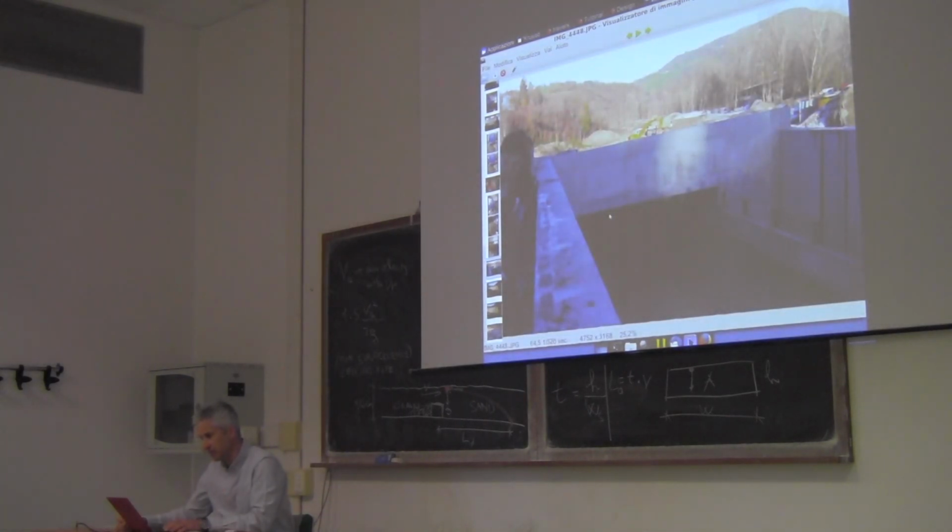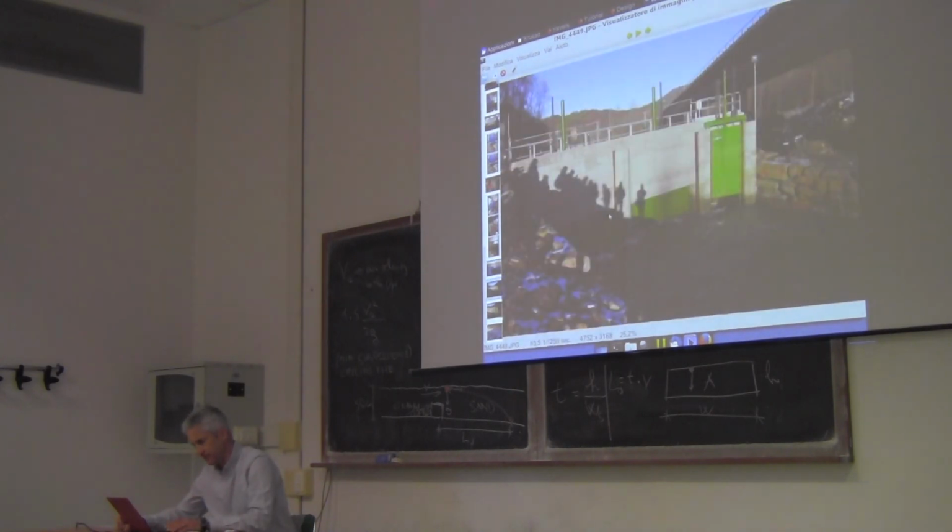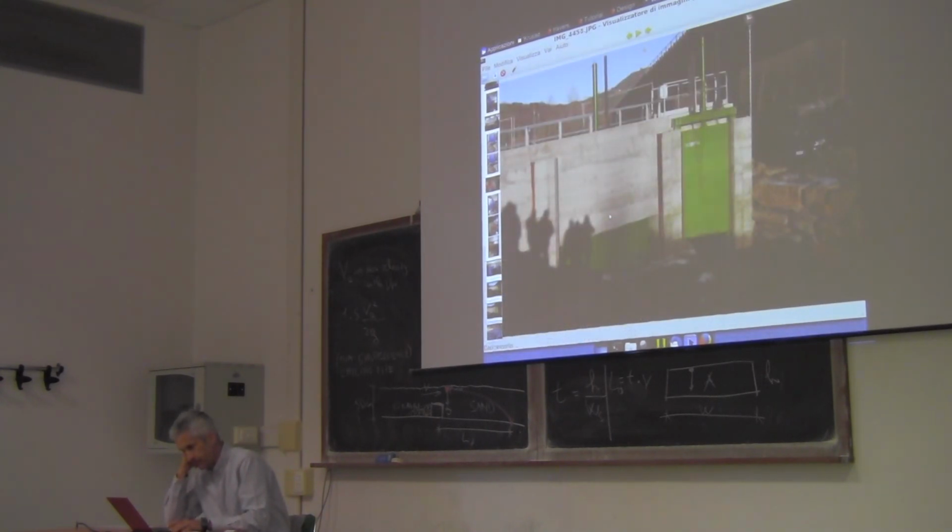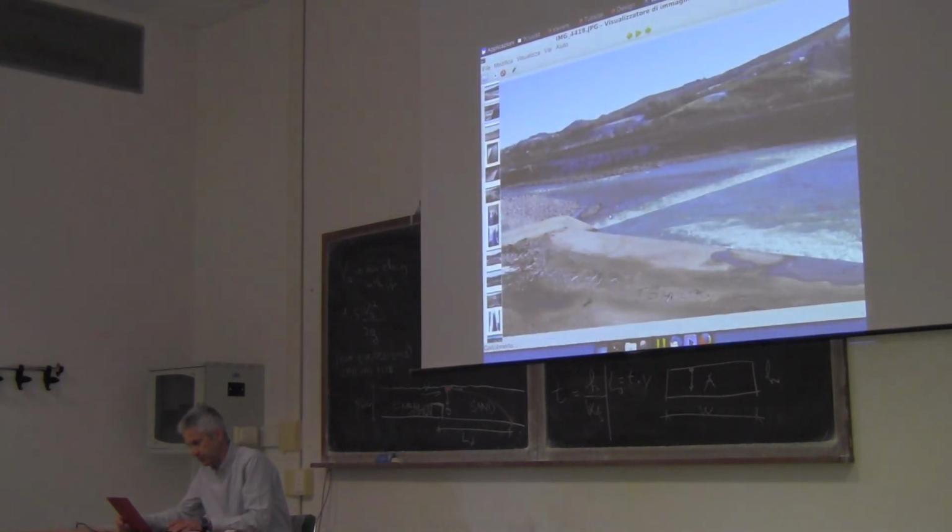And this is the canal that you have seen before during construction, with the water flowing. And you have seen pictures during construction before of these gates that are maneuvered in order to bring water. The big one is the water that is delivered to the turbines. The small one is opened in order to evacuate the excess flow and bring it back to the river. Okay, that's it.